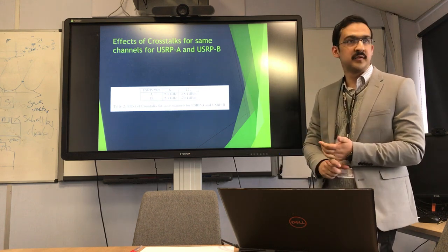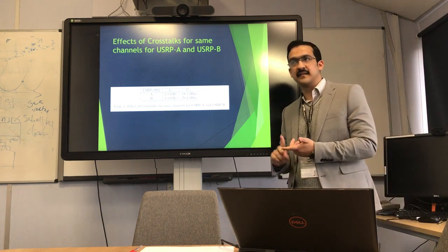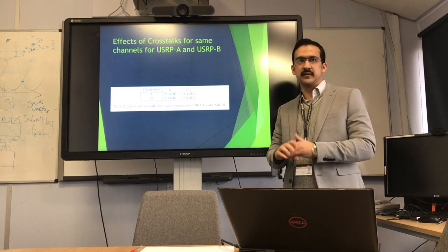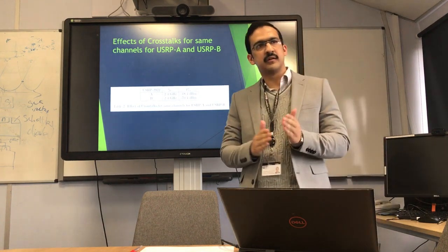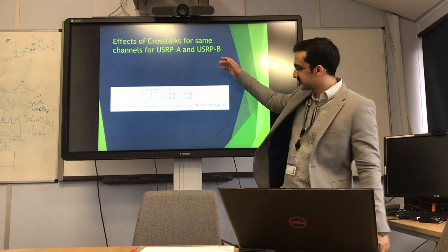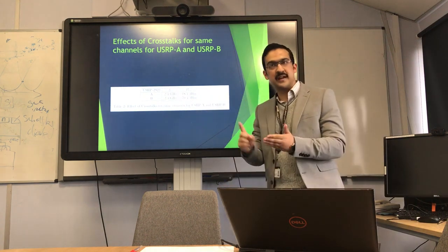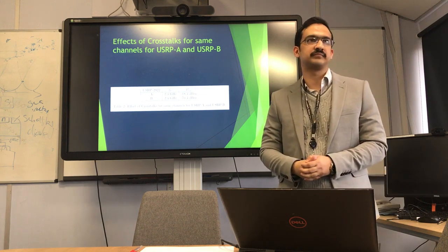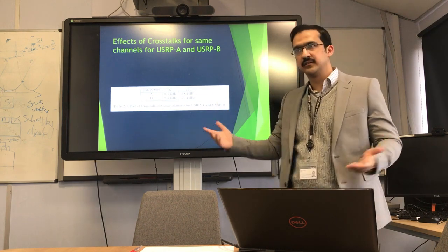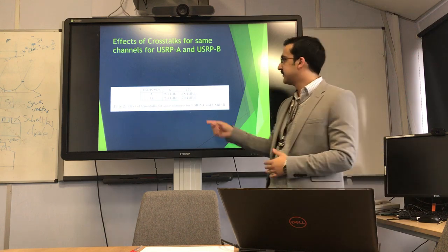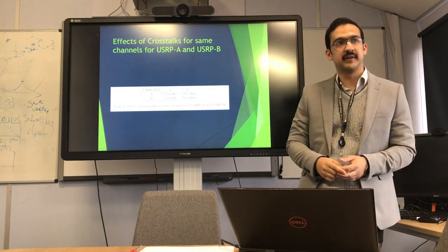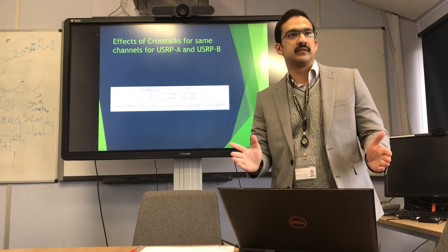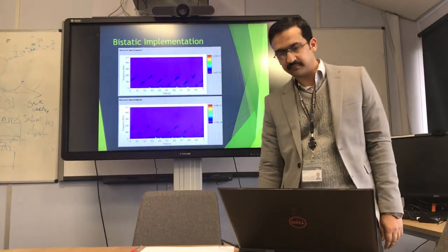The point to notice is that each device has its own crosstalk. Although you expect it not to cross a certain threshold, this looks quite high, but since these are old devices, there might be some issues inside. You should keep that in mind and first try to figure out what the corresponding crosstalk is. You can see there is a huge difference between the crosstalks for the same model on two different devices.